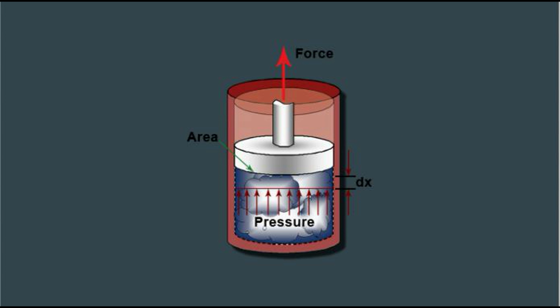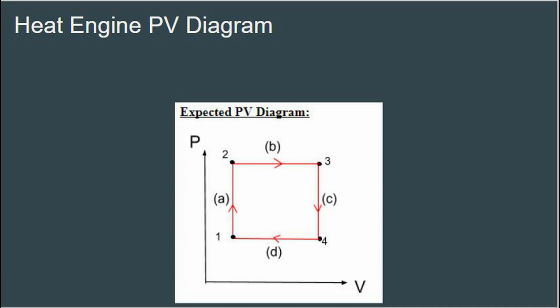Our heat engine takes advantage of the change in volume of air in a sealed canister piston system to do work by increasing the gravitational potential energy of a mass. We started with our cylinder in the ice bath. This correlates to point 1 on our PV diagram. The first phase of our PV diagram, from point 1 to 2, was isochoric expansion. This phase occurs when the cylinder is removed from the ice bath and placed into the hot bath.